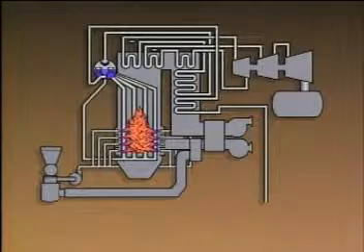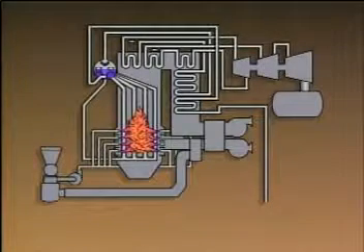In addition to the 4 elements that are needed for any type of combustion, combustion in a boiler requires 2 additional elements to control combustion so that it's efficient. These elements are turbulence, to mix fuel and oxygen thoroughly, and time, to allow the combustion to be complete. Let's look at an illustration of a typical boiler to see how each of these elements fits into boiler operation.